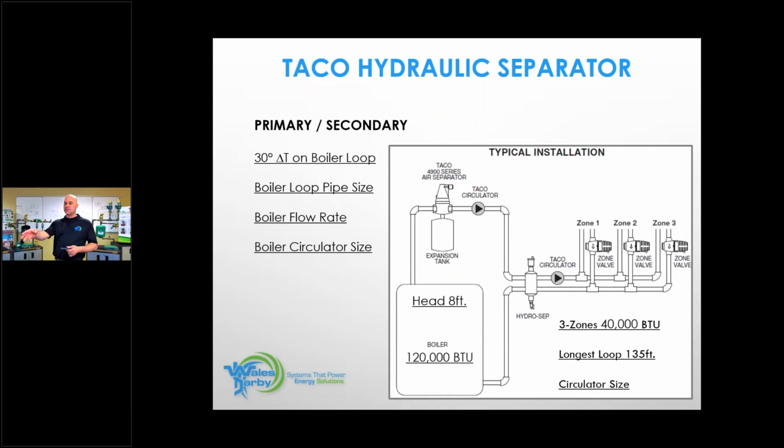And that's a hydro separator with an air can on the top. It's more of a hydro separator than an air separator on that system. There's a bunch of different ones made out there. That looks like the Taco version. It's basically just a copper diameter pipe, has the air separation on top, and then has your closely spaced T's coming into the sides of it, and then it has a drain on the bottom. So that's more of a hydraulic separator.